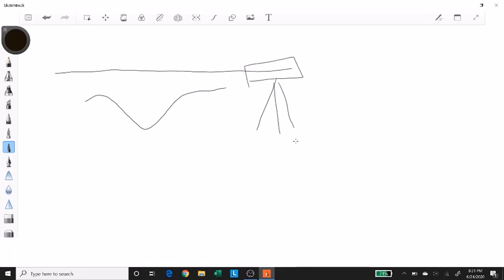And this becomes my line of sight. I want to find out the elevation difference between these two points. In one case, I place my leveling staff over here. In the other case, I place my leveling staff over here. Now remember, the 0 for both starts at the base of the leveling staff. So the 0 is same.